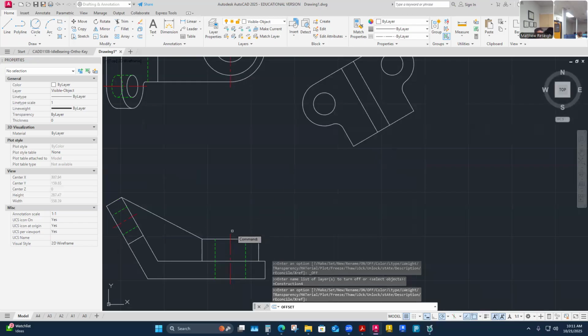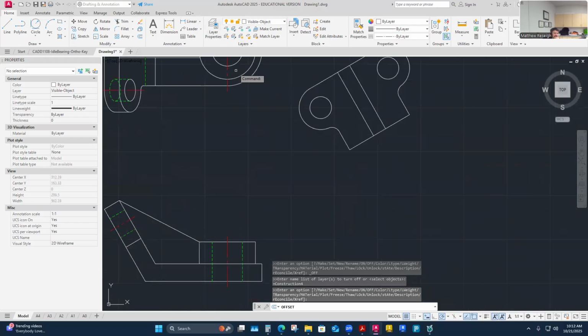But yeah, you're right. If I was going to show a full auxiliary view, I would have to project this stuff across and get another ellipse and some foreshortened looks here. I feel like it's pretty common to do partial auxiliaries just to expose what I'm truly trying to dimension. This would be undimensionable material here, and I'm going to be able to dimension that stuff here and here.